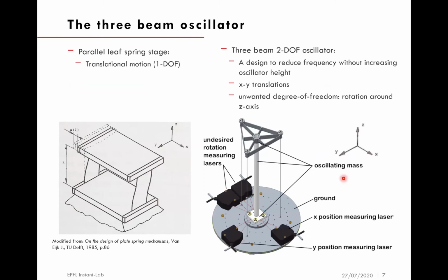The center of gravity of the oscillating mass is located at mid-height of the flexible beams. For this reason, the oscillating mass consists mainly in this long bar. Moreover, this shape reduces the inertia in rotation around the z-axis, which increases the frequency of the unwanted degree of freedom in rotation. As mentioned before, the oscillating mass has a square-shaped part at its base.